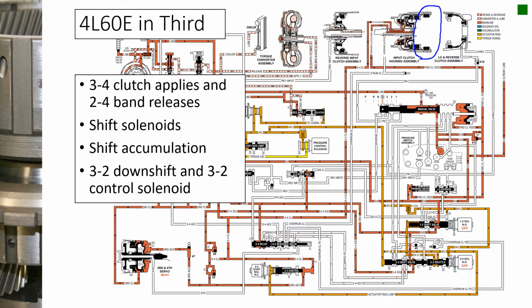A lot of them will also break a sun shell. That's really common, especially the older ones. And then some of them will run into sprag issues. But those are the 3 areas that are probably their weak links. And there's a lot of aftermarket considerations you could take for those.